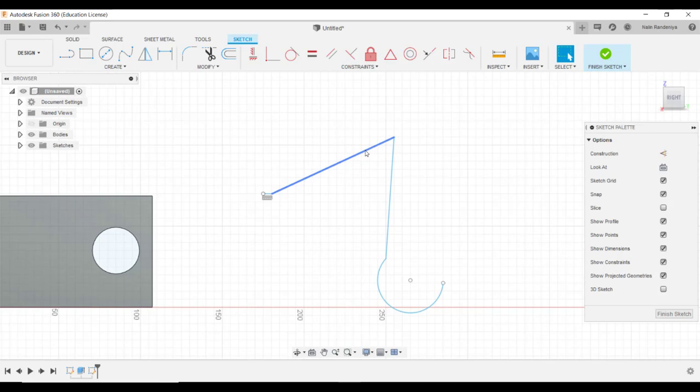So right now the line I have my mouse pointer on and the other one are at a random angle, because I didn't specify any angles when I was drawing them. So even after I draw them, I can just simply go into perpendicular. Notice after I clicked on that, the mouse pointer changed according to the constraint I selected.